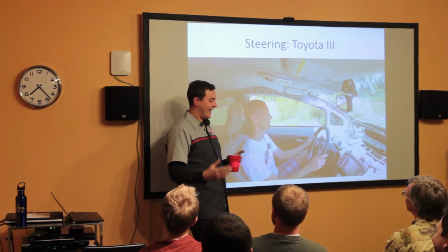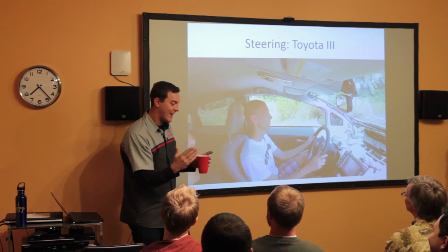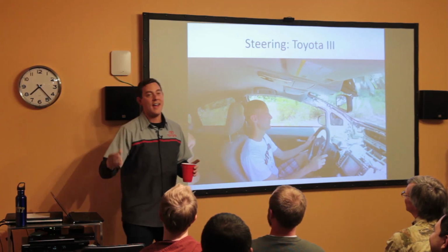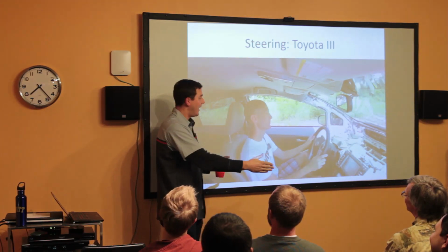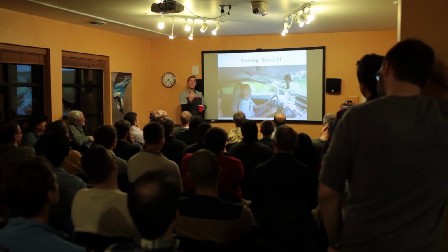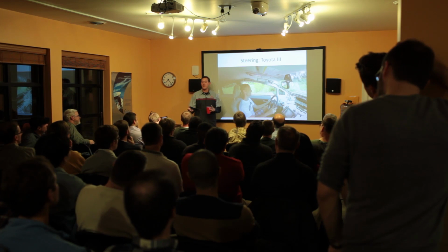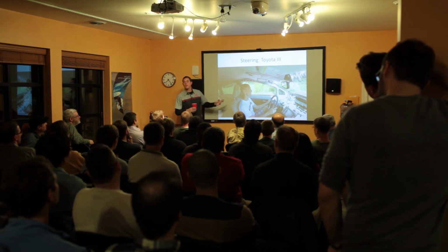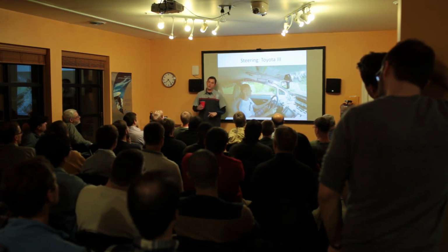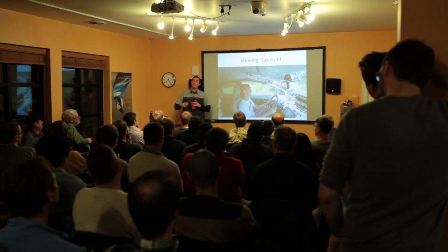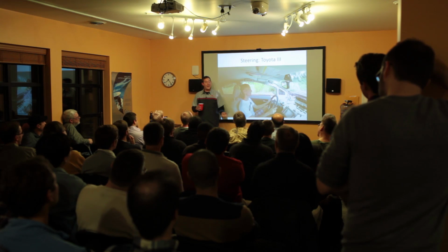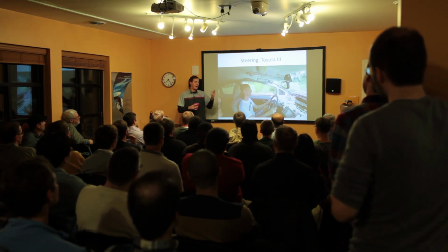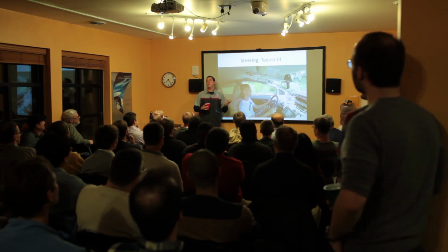And I got 2 ECOM cables at that point, and I flooded the network with one, telling it was going the speed of light. And we sent an invalid speed message so quickly that ECUs that were dependent for steering decided to go offline for a little bit. So we'd knock these ECUs offline. The moment that happened, we'd then send the packets like, hey, turn the steering wheel the whole way to the left. And you'll see the steering wheel do counterclockwise rotation here.